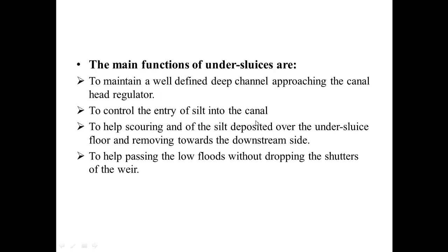Number 3, to help scouring of the silt deposited over the under sluices floor and remove it towards the downstream side. Means that the silt which is deposited at the diversion headwork is removed through these under sluices or scouring sluices and moved towards the downward side.